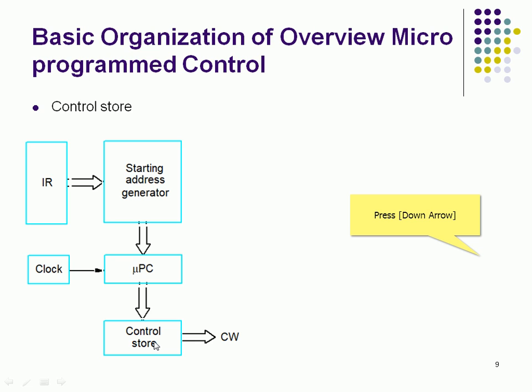So that is a control word coming from the control store. The micro PC holds the address of that micro instruction. In the previous example we saw T1, T2, T3, T4, T5, T6, T7 and so on, where only 7 clocks were there. In a big program, many clocks will be there, so the complete set will be a bag. The control store and the micro PC tell us which micro instruction we need. We have to identify it, and the corresponding micro instruction will be brought out, right?